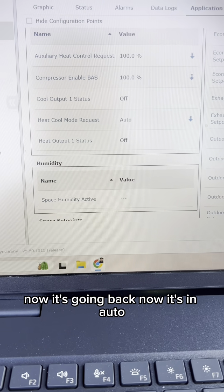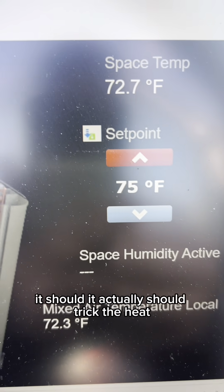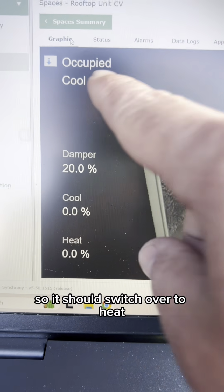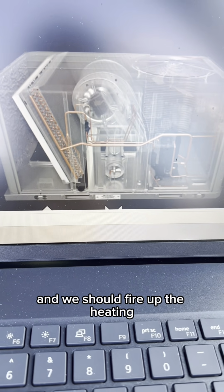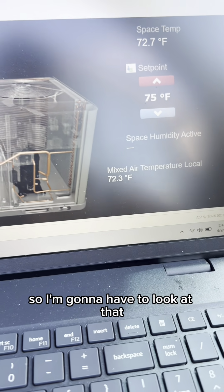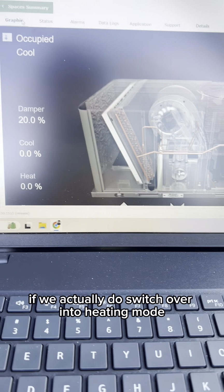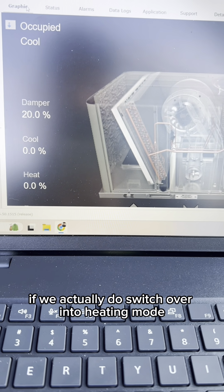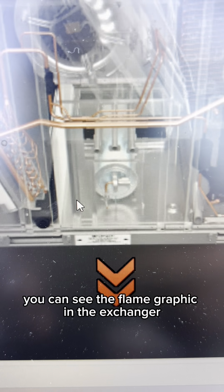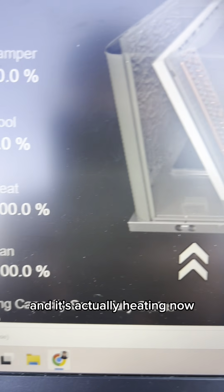Now it's going back, now it's in auto. And if we go back to the graphic, it's probably going to stay in cool. Actually, no, it should switch to heat because right now the set point is 75. So it should switch over to heat and we should fire up the heating. Another issue I'm having right now, I noticed, is that there's no humidity reading. So I'm going to have to look at that to see why we're not getting a space humidity reading. So let's give it a moment to catch up and let's see if we actually do switch over into heating mode. There we go. Our heat went to 100%. And if you look, you can see the flame graphic in the exchanger and it's red. So right now it is saying it's in heat and it's actually heating.